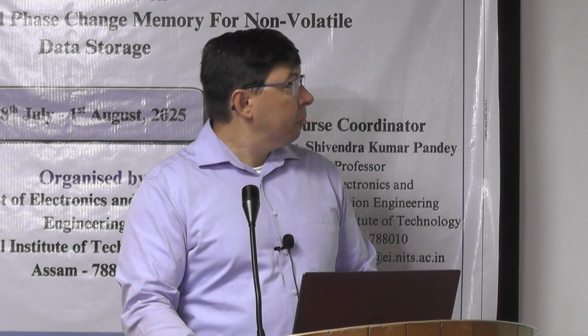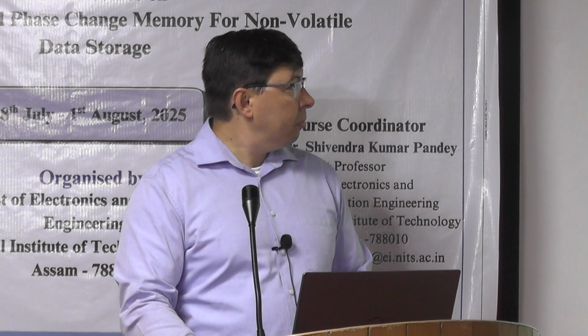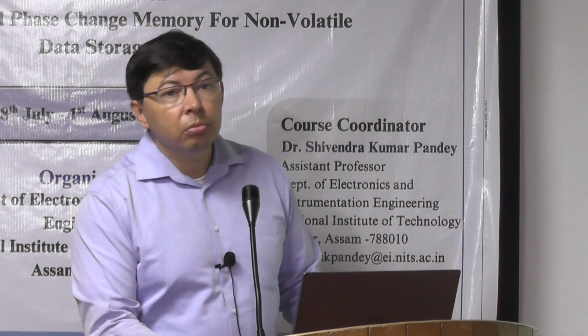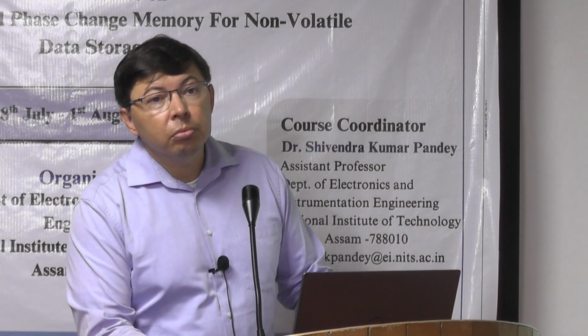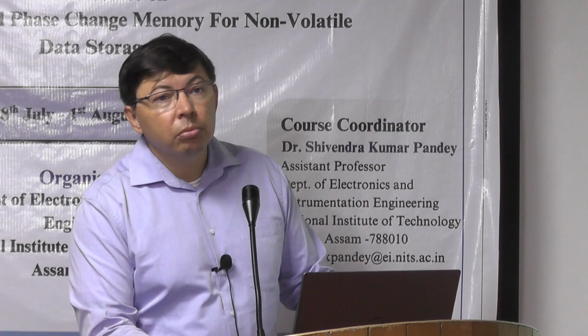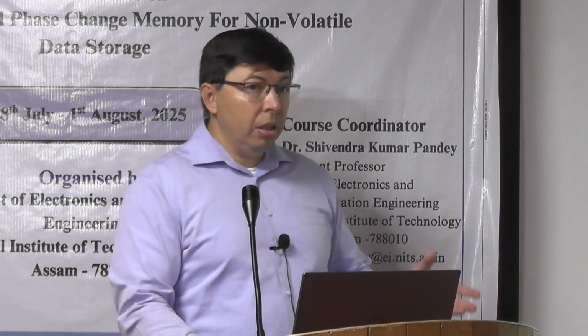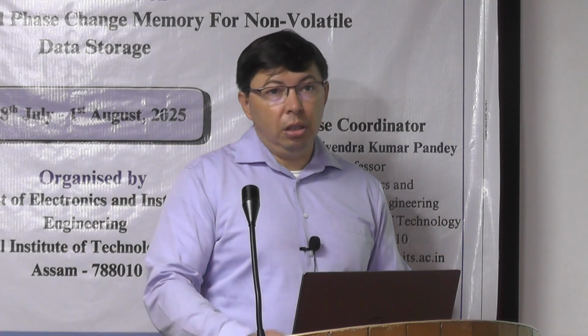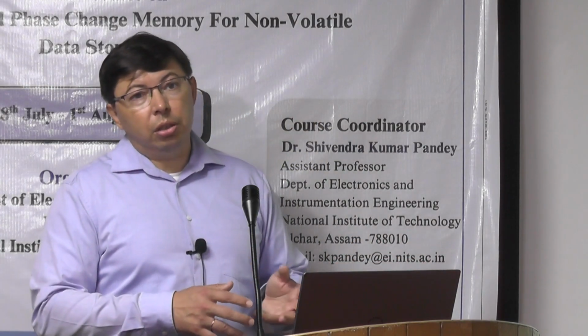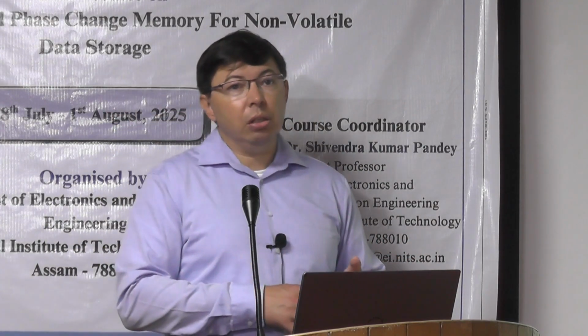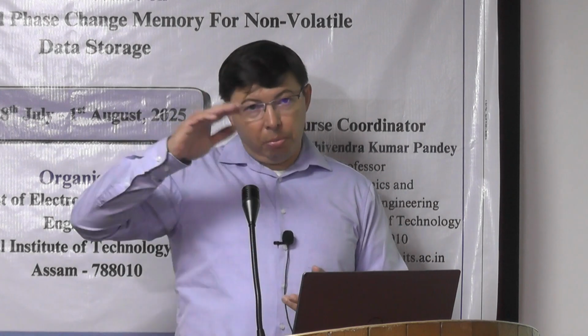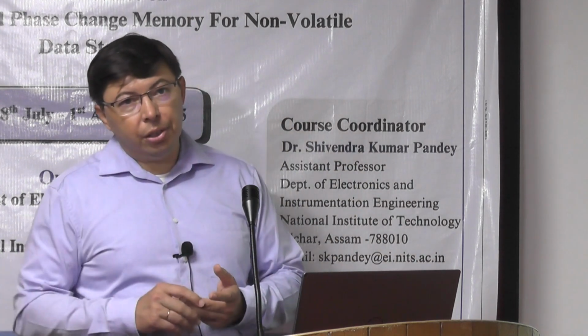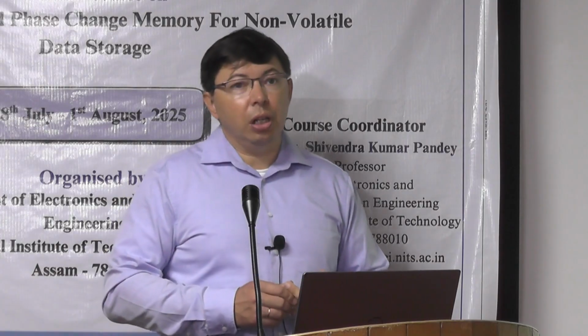I did not catch GST 225. Does it show both metallic and non-metallic behavior? It shows metallic and non-metallic behavior. Yes, the amorphous and cubic phases are non-metals, and the stable trigonal phase shows metallic behavior.